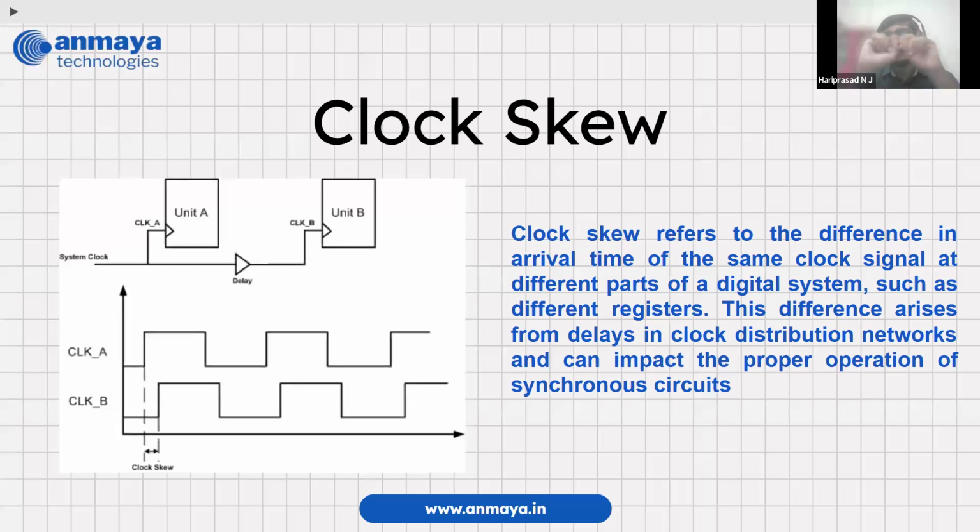If you use that generated clock in the sensitivity list, like always at that generated clock, you're going to spoil the clock path, right? I mean, your data path is forwarded to the clock path, and you are messing up the thing. So you will definitely see violations when the design becomes congested.